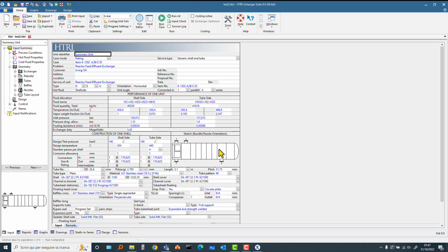Let's say other characteristics. If we look at the quality, the quality is the percentage of the vapor weight fraction. On the hot shell side fluid, we have 1, so 100% vapor at inlet, and 0.9 and something at outlet. So that means that there is a condensation of a very small fraction, less than 10%, but there is a condensation.